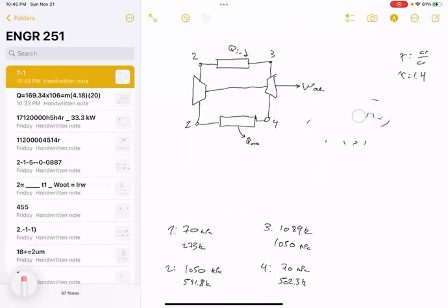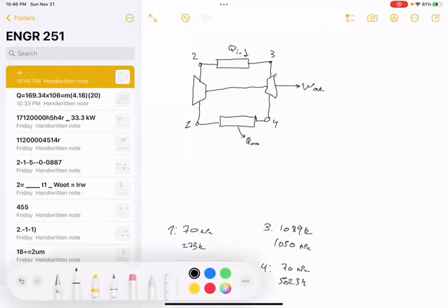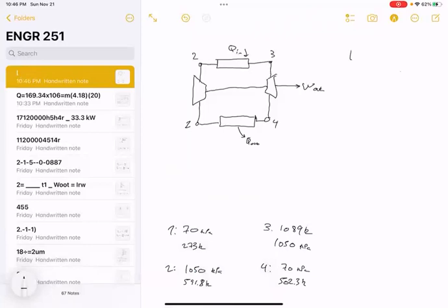Okay, so the power output is what happens in the turbine, but we have to consider that a good amount of that power is going to get rerouted to the compressor. So let's see what happens. M dot Cp delta T across the turbine corresponds to our 1 kilogram per second times 1.005 for air, which is Cp of air, times delta T. So T3 minus T4. In other words, 1089 minus 502.3. Now let me calculate that.